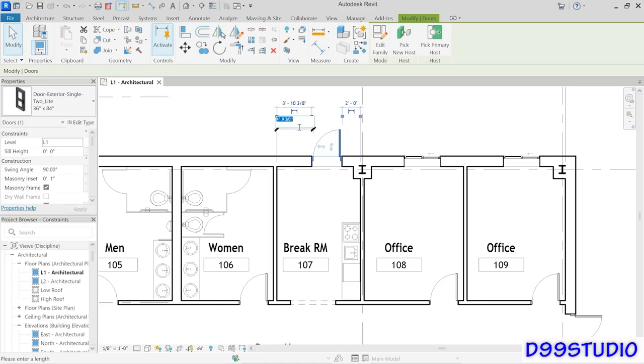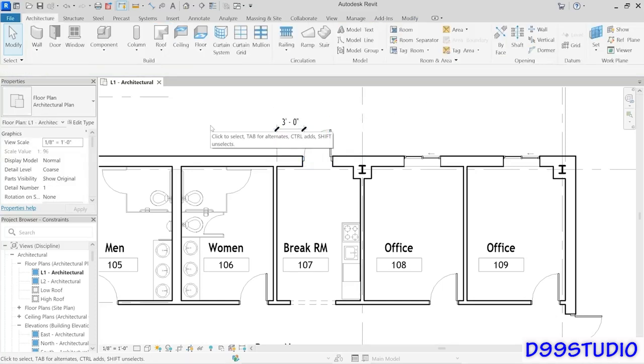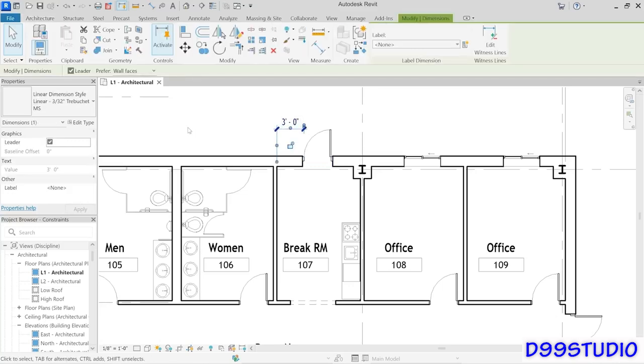And let's say I wanted this distance to be 3 in imperial or 900 millimeters in metric. So I'm going to put that in, enter it, you'll see the door move to that position. But now it's important to my design that that door doesn't change, doesn't deviate from that location. So I'm going to come back and select the dimension, and there's a padlock right here. You just simply lock it.